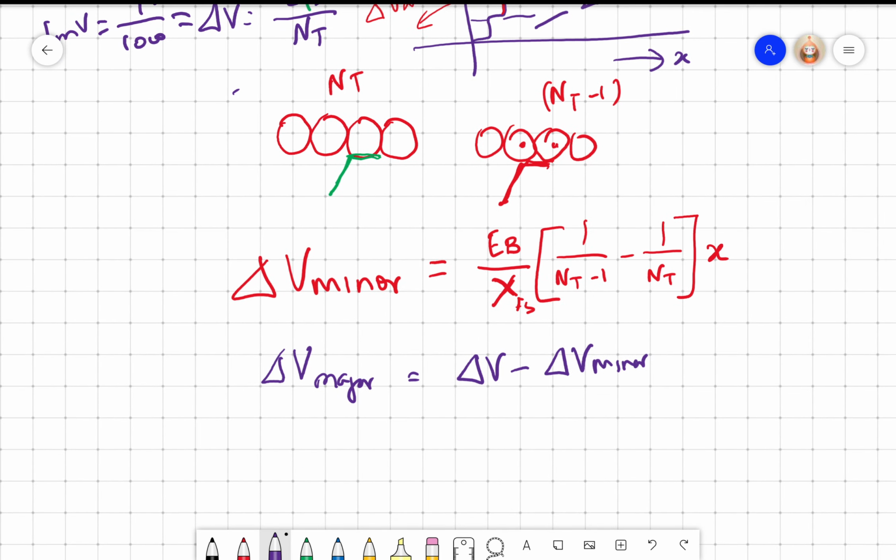The wire wound resistive potentiometer type displacement transducer suffers from the minor and major resolution pulses. Right? Again, this is not a big problem. We can continue to use this. Right? So we can make, as I said, a linear displacement potentiometric type transducer or an angular type potentiometric transducer, to measure angle as well as displacement x.